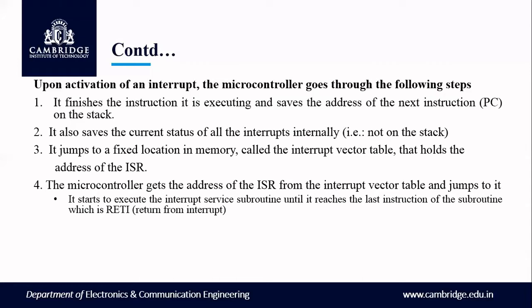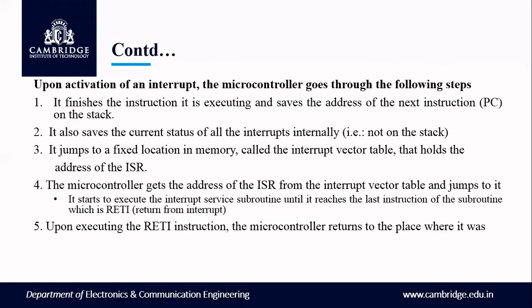Until that, it will be executing. Once it comes to RETI, upon executing the RETI instruction, the microcontroller returns to the place where it was interrupted. This is very important, where it was interrupted in the main program. So the RETI instruction retrieves the address stored on the stack, and it points to the next instruction in the main program.